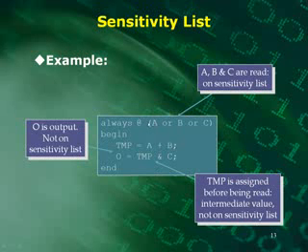Okay, let's go to the next thing here. Here's another example. Here we have another always, and our sensitivity list has A or B or C. Now output doesn't have to be on the sensitivity list. This O doesn't have to be on the sensitivity list since it's an output.